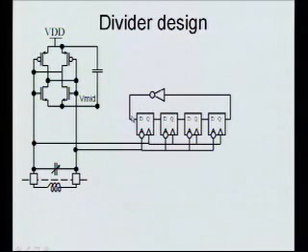So you can imagine if, say, we started with this input at 1 and everything else 0. Then after one cycle, that 1 propagates to here, and then to here, and then to here. And after the fourth cycle, it's to there, and that comes through the inverter and makes this a 0. Now the 0 propagates through. And so a total cycle takes two propagations through this loop, or 8 cycles, and so it divides by 8.